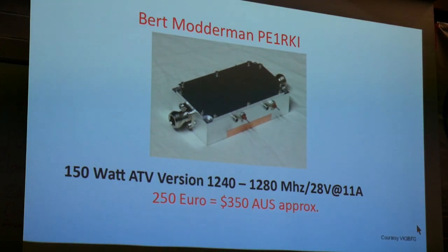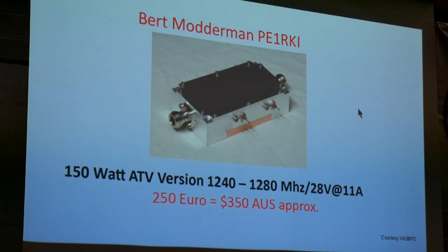Of course, this needs a big heat sink, right? This is 150 watts. If that's 150 watts RF out there, you've got about 300 watts here. I don't know, yeah, they're not so efficient, these things. So you've got this on a really big heat sink with a load of blowers. Class A, won't they? They're not going to be linear enough unless they're really Class A, aren't they? Yeah, well, that's true, but of course you always push it as hard as you can go, right?